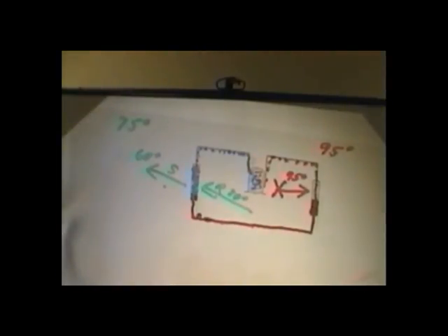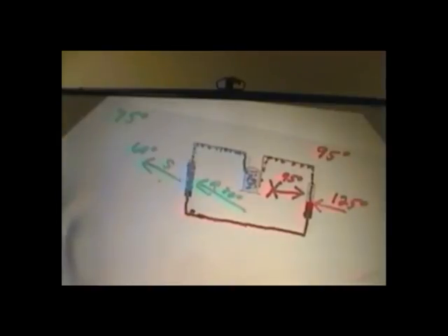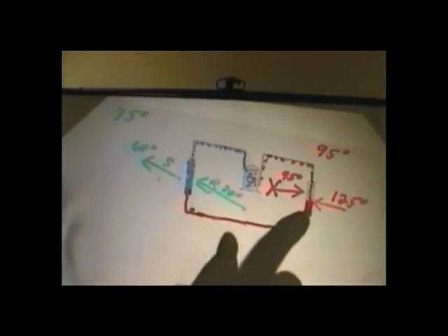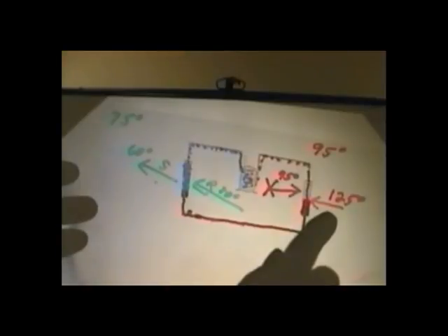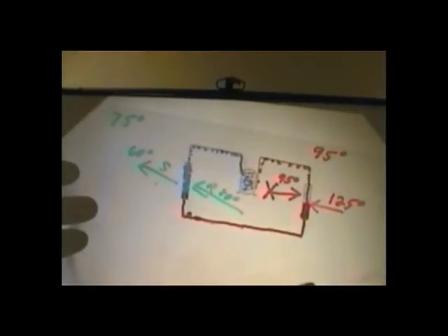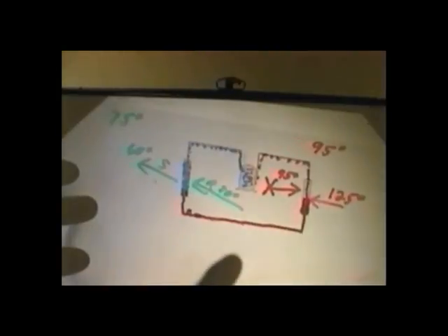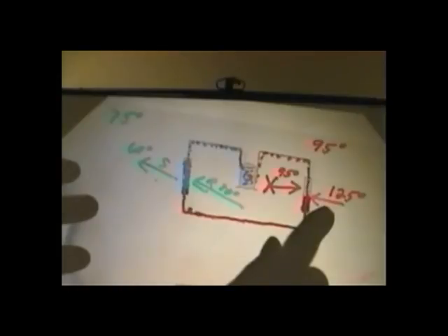So if it's a 30 over ambient condenser, and if we know that the outdoor temperature is 95 degrees, this condenser would be what temperature then if it's 30 over? 125 degrees. But what we have to understand is that it is 125 degrees in one place only, right there where it's changing state. That is the saturation temperature. Above it, it's hotter, below it, it's cooler.